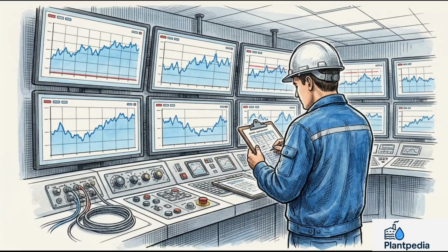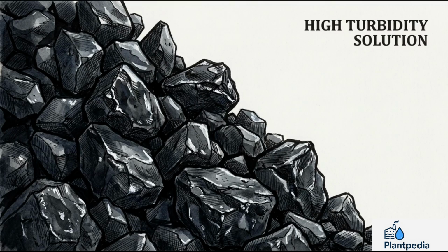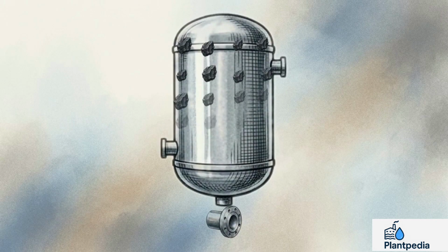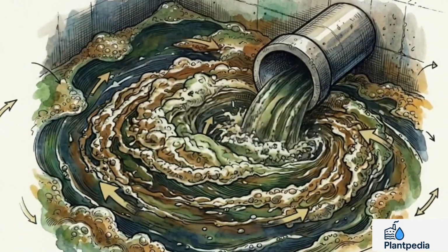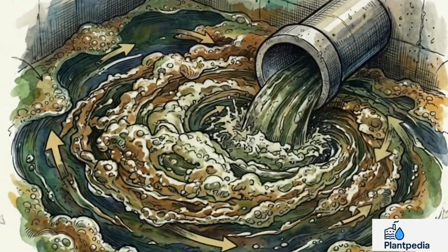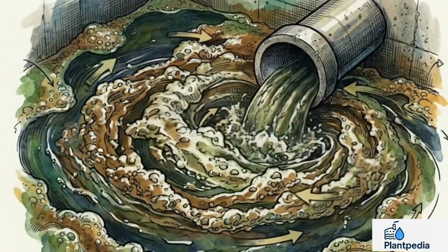downstream processes. There is one major exception to the multi-layer trend, the pressure anthracite filter, or PAF, which uses an exclusive packed bed of crushed anthracite. Unlike smooth sand, anthracite particles are angular and lightweight, creating massive empty spaces between the media. As heavy organics and oil flow in, they adhere to the rough coal edges. These large void spaces absorb heavy solids without abrupt pressure spikes. Engineers deploy PAF systems specifically to prevent system choking in heavy effluent treatment plants, handling high turbidity water and heavy organic loads.